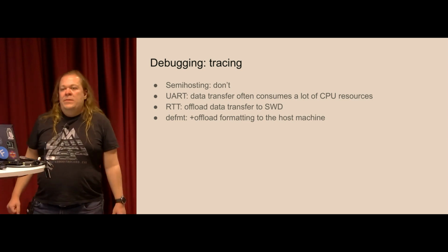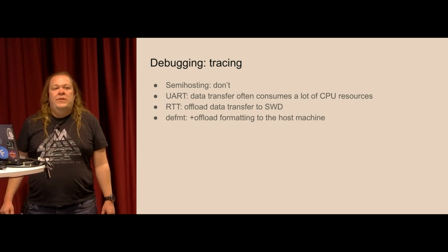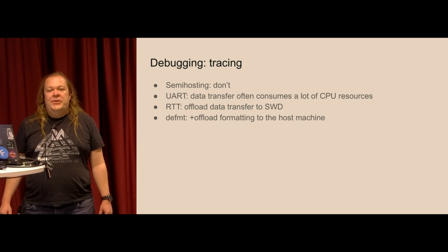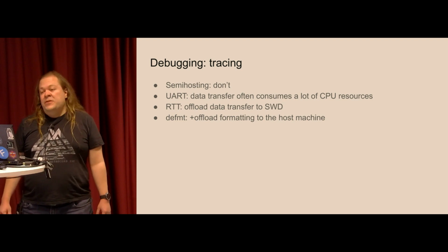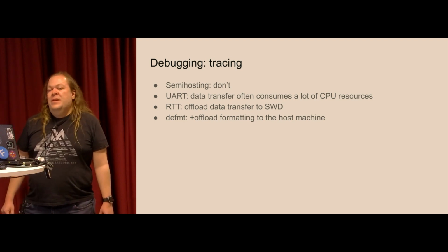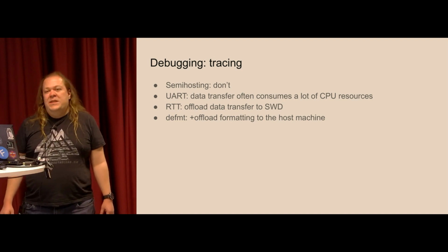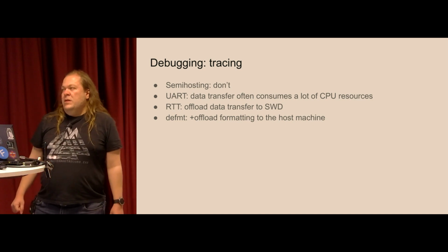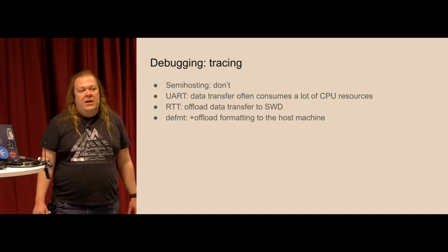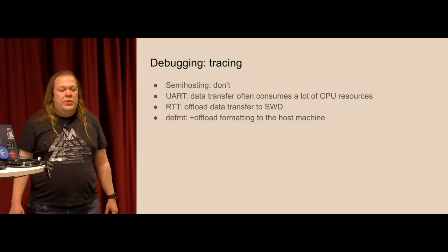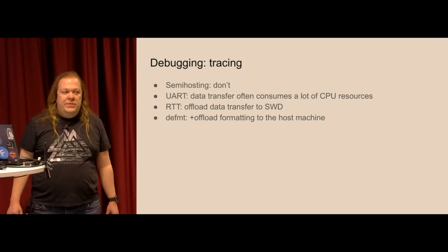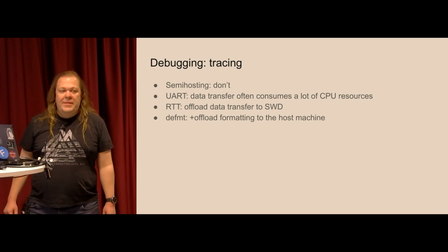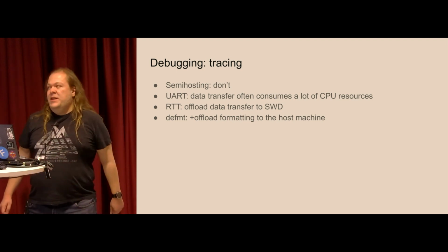world. Semi-hosting is quite good in a way that you can work even with files on your host PC, but from the microcontroller. But it is really, really slow. And if you try to just send some bytes over it, it will be super slow. It is not suitable for debugging of USB, and I would think that with modern approach, you shouldn't use it at all and don't let anyone use it. Like friends don't let friends use semi-hosting.